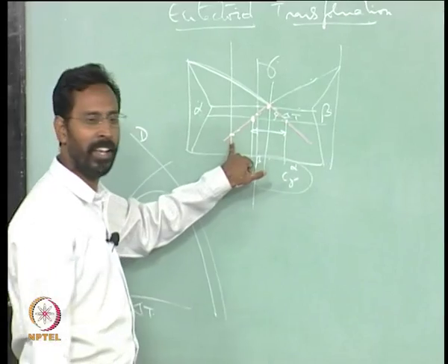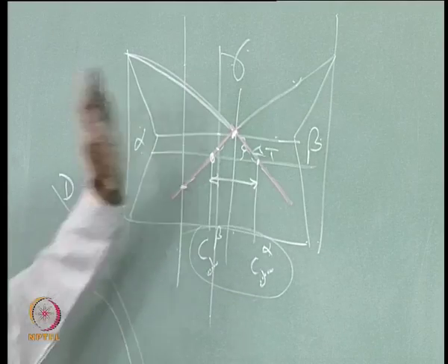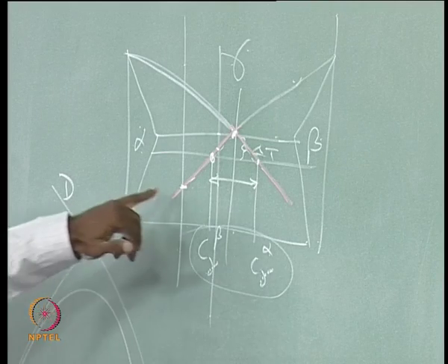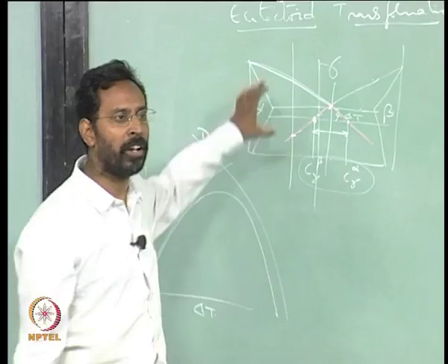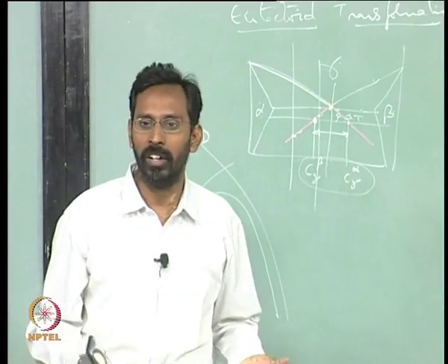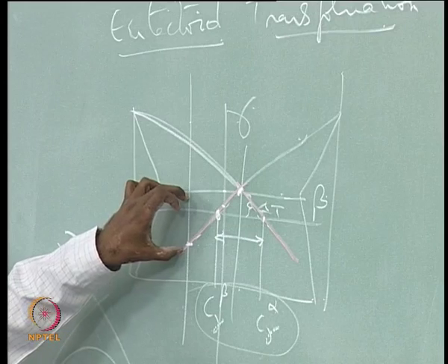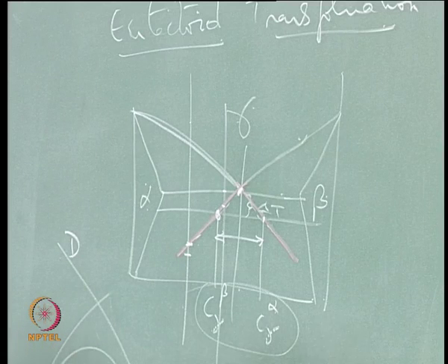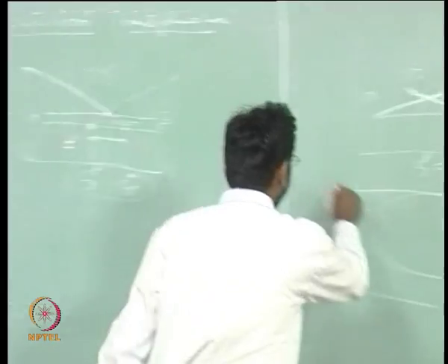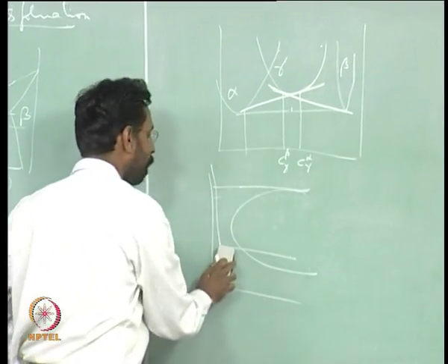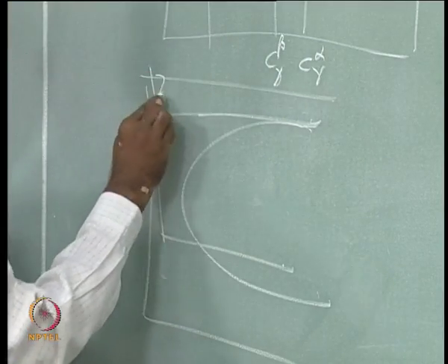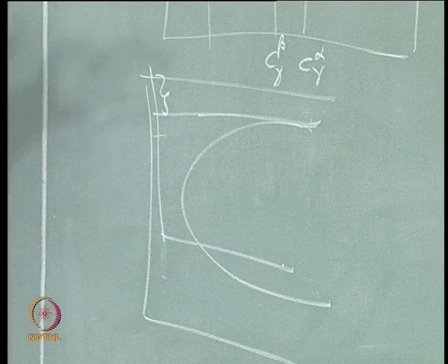But if I take this alloy, which is farther from the eutectoid composition, and I can undercool it, of course undercooling that alloy to that temperature is also not easy, because the extent of undercooling that I need to provide is very large. If I can somehow provide that undercooling and hold it at that temperature, you would end up in a bainite. Though there is a pro-eutectoid phase, no pro-eutectoid phase will come out during this undercooling, because you are cooling it fast, you are not allowing time for the pro-eutectoid phase.